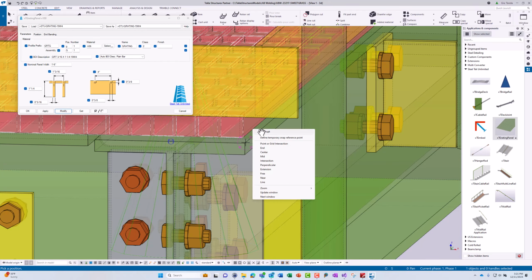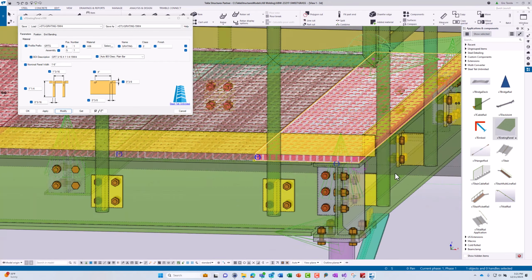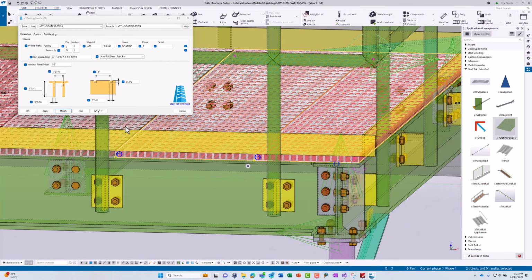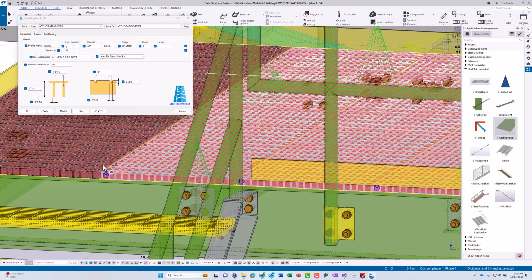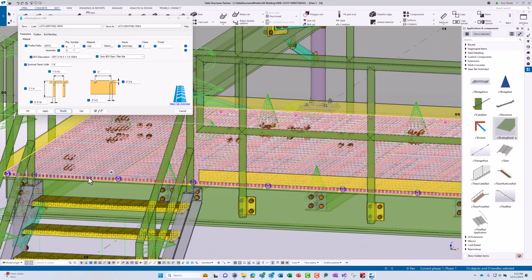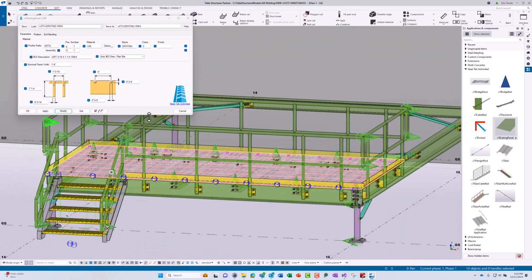After modifying the last panel, we see we have about a 1/2 inch gap on the end, so we can select all our panels and move them a 1/4 inch to the right. Then we will have approximately a 1/4 inch on the left end of the platform and a 1/4 inch on the right end of the platform. We use the Move Linear command in Tekla to do this.